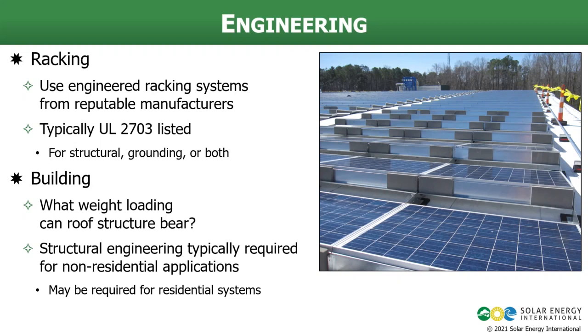I'll tell you a story. We had a system in Connecticut that we were proposing for a residential customer. We did do a structural analysis from a professional engineer, not a stamped plan, but a quick overview to see if the building could withstand the weight of the PV system. And it turned out that that structure failed the structural analysis by the engineer. The roof structure needed reinforcement. We proposed a change order to do that reinforcement. The customer did not want to pay the extra for that structural reinforcement, so we did not install that system because the building could not support the load.